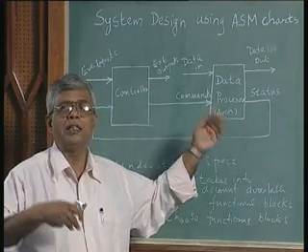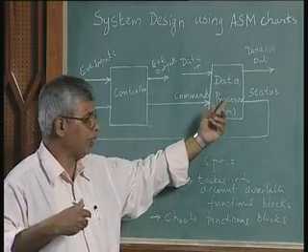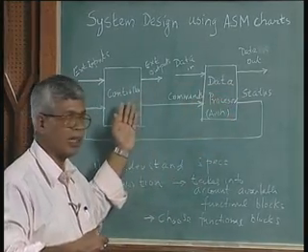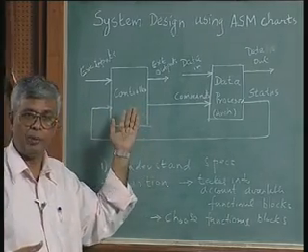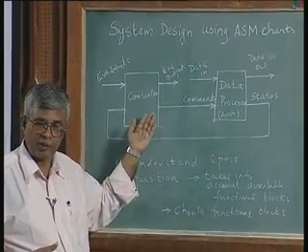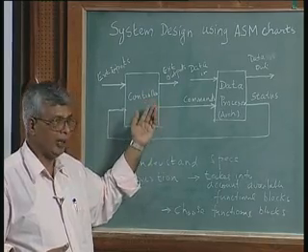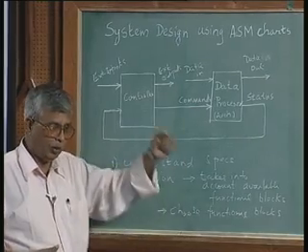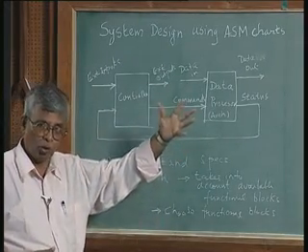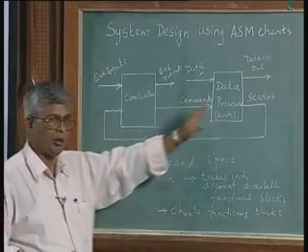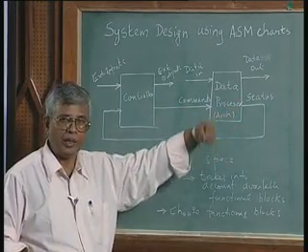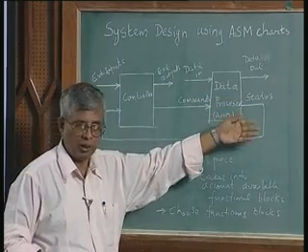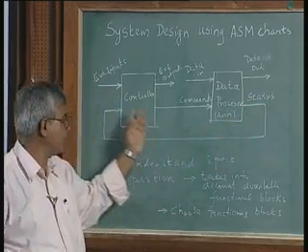So I would not like to do 16 times something here. When you put the 16 times here, my state graph is going to become extremely big. 8-bit multiplier, 16-bit multiplier. For each multiply I put a state, multiply, add, shift, each is a state. I do a big state graph, the controller or the ASM chart will be so big with so many states. Instead I can put a counter here, activate the counter, and every time I do a shift, increment the counter by 1. When the counter reaches a particular value, I compare the value and then give the signal.